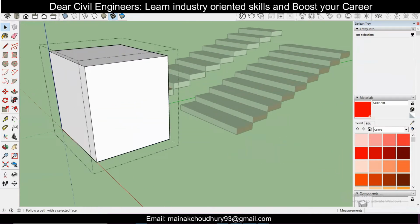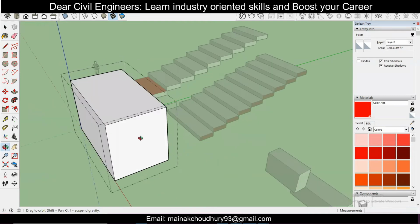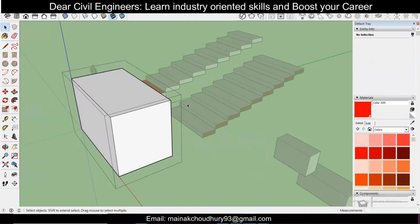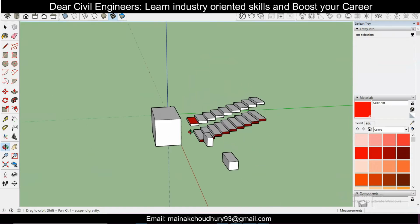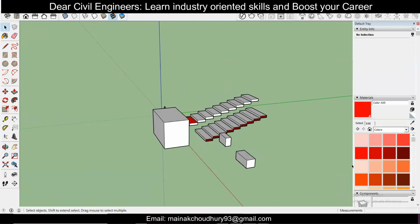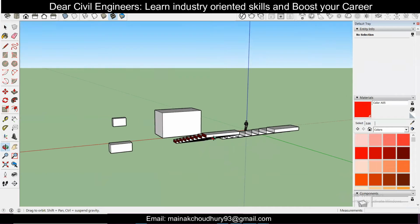Suppose I want to extend this face here, I'll use the push pull tool to extend this. So if you double click and then enter it, you can make any changes. So I'll use the select tool and click outside to escape out of it. So these are some uses of groups and components. So for understanding this even better, let us make something.